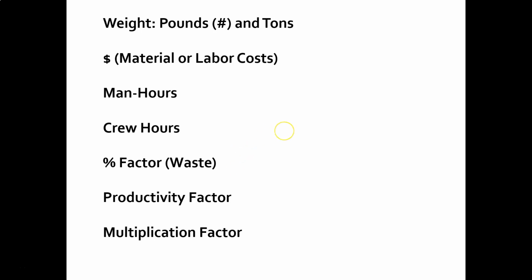So when we get to our final number and figure out how many sheets of drywall we need for the house, we often will add like 10%, because we know that certain materials have a lot of waste. Now, obviously, doors and windows, there's no waste, but other drywall being probably the biggest example, plywood, lumber, concrete. With concrete, they do put numbers in, but I don't think a lot of concrete actually gets wasted. It has to get disposed of. Hopefully not.